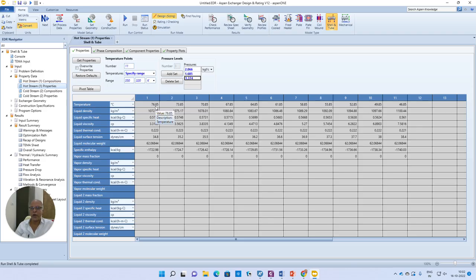So it calculates within this 3 degrees what the various properties are. So at 76.85, what is the density, specific heat, viscosity, and so on, which are needed for doing the design. Similarly, for the next 3 degrees, what are the properties? Until you come to the last zone. So you can see the variation, 1072 to 1100 in terms of density, and especially in viscosity, 3.3 to about 7.5. Calculating these properties in such small zones may not be possible when you try to do it manually. That could be one issue.